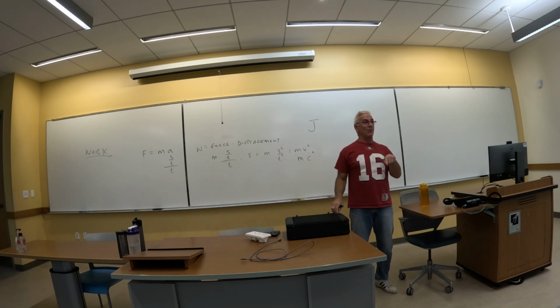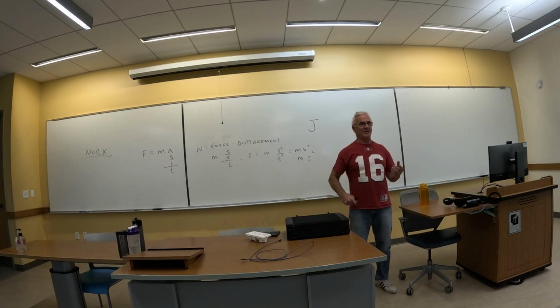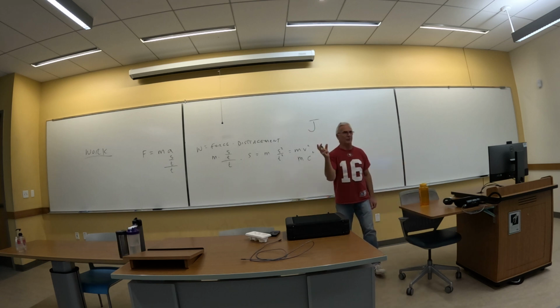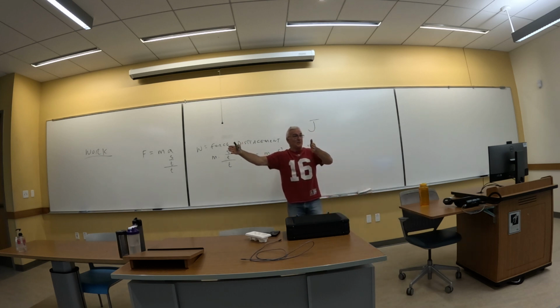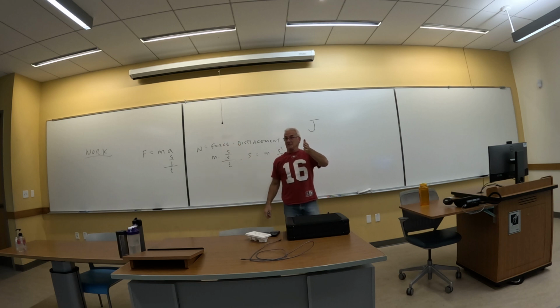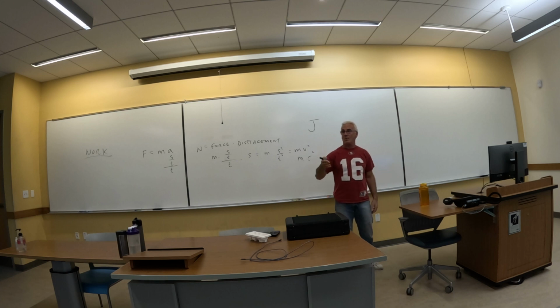That's why it's kilowatt hours, because when you're looking at your light bulb, how long you leave it on is also how much you're paying, isn't it? It isn't just, oh, there's a very powerful light bulb, I just won't turn it on. Well, no, it's how much energy am I using per second. Kilowatt hour means I'm multiplying by 3,600 seconds. The kilowatt means there's also 1,000 of those, 1,000 watts. So that's all what the watt is.